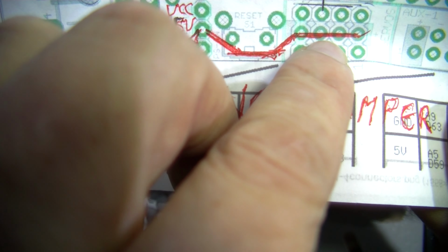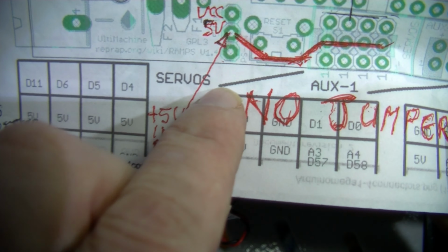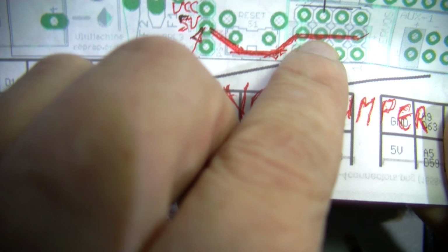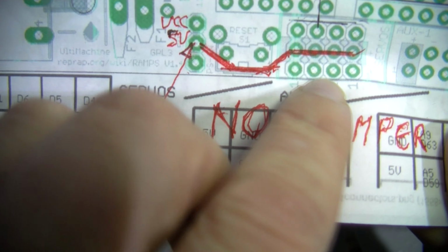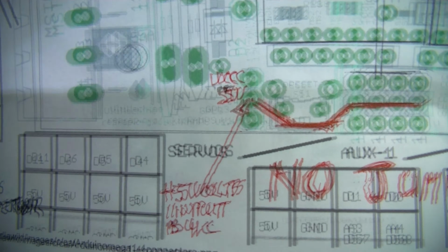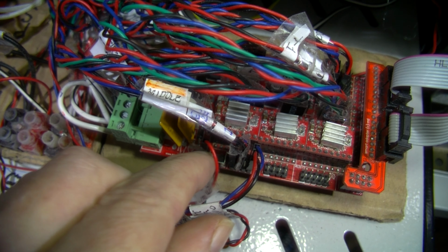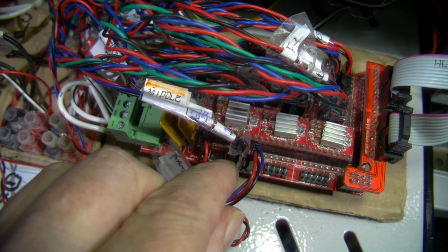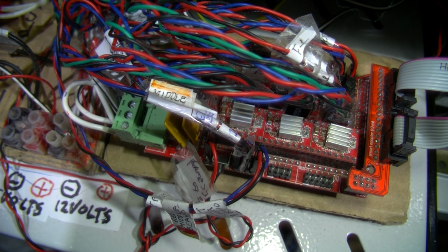Come on, I'm trying to get this into focus. There we are. And it goes along all this row of pins for the servos. So these are the servo pins up there. So all that whole row there is 5 volts. So far as I know, this is ground this way, and the top is really the signal for the servos or whatever you're using. As I say, I'm using mine for BL touch, filament runout sensor, and a servo. And the servo is used like a wiper arm to clean filament off.